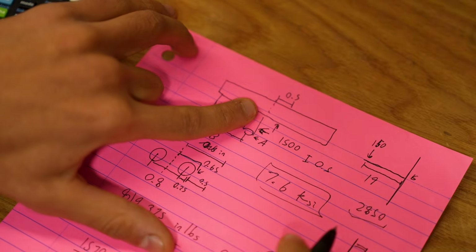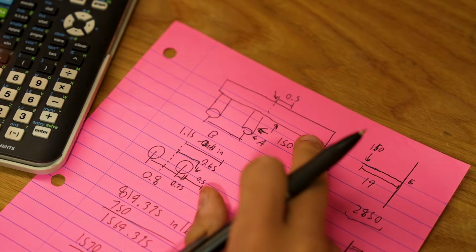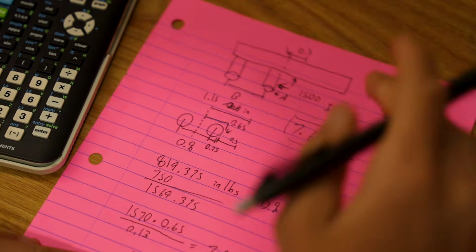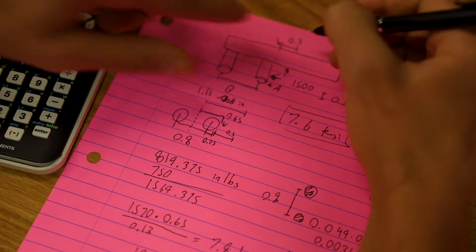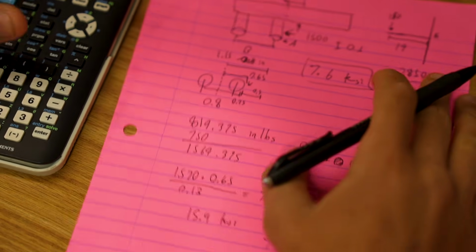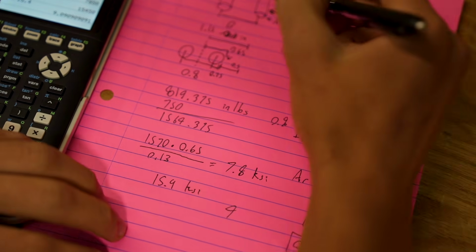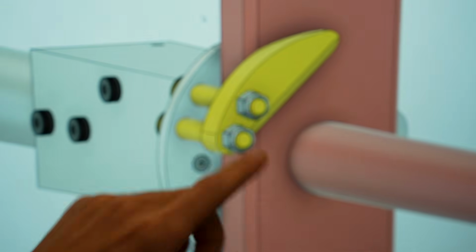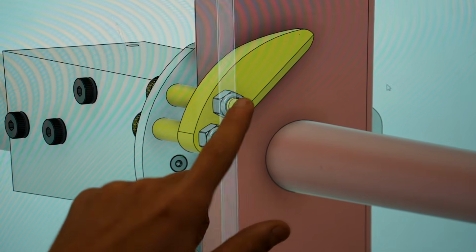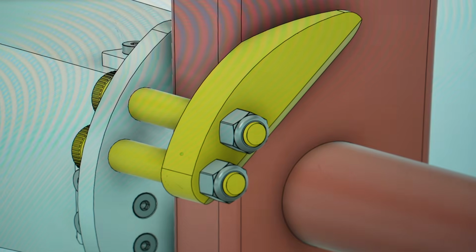is to define the stress at this point here, right? This is made of aluminum. Aluminum is kind of like weak, mushy metal. Fake metal. It really is in a sense. So we're going to make sure that we're not yielding at this top point here. So that's going to be just a pretty straightforward MC over I calculation. Our cross section looks like this. I can just measure it live. So we're going to be looking at the cross section of our hook at our point of interest.